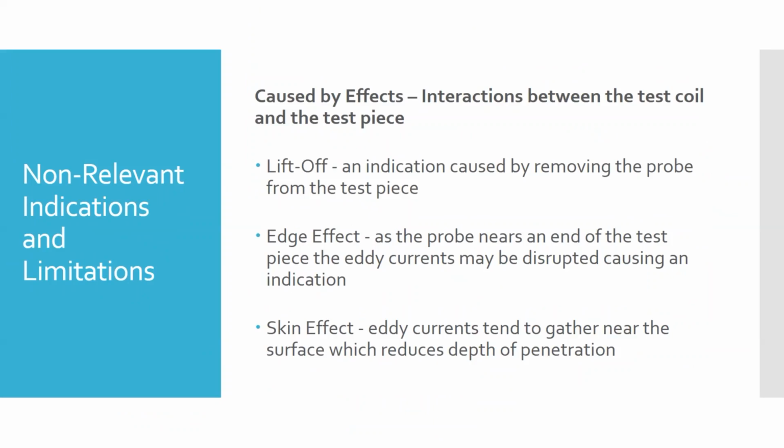Whereas if you have a multi-frequency device that can do that all at once, with multiple coil sizes that can cycle the different frequencies, you may be able to do the inspection faster in a single pass, that kind of thing.